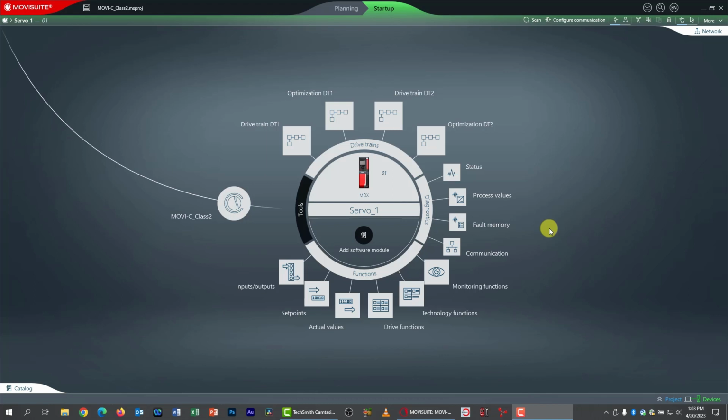All right, well, we're going to play with the MOVIKIT now. We're going to add the Velocity Control Drive Level MOVIKIT to our VFD and give it a try. I'm still in ELSM mode with my encoderless servo, or what's simulating one. The Velocity Control MOVIKIT can run open loop, which means it can pretty much run on every single motor that the VFD supports. So let's go ahead and get started.